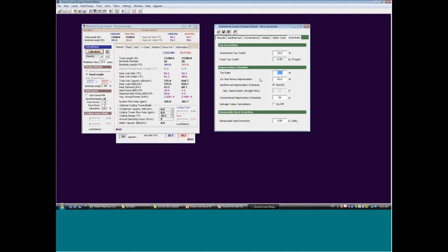If there's any bonus depreciation, you can put that in here. A couple of years ago, it was 100%, then it's dropped to 50%. It's going to drop to 0. So we'll just leave it at 50% for this example. For the geothermal system, we can define the depreciation schedule. MACRS, which is that accelerated schedule, is very beneficial. Also, I'd recommend if you are designing a system in a location where it's offered, just leave that on. If you don't have that, but there's other incentives, you can switch that off.